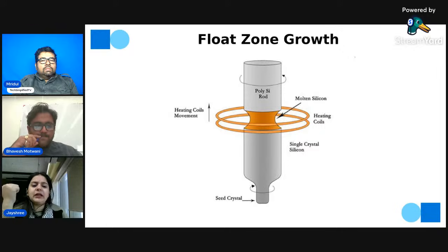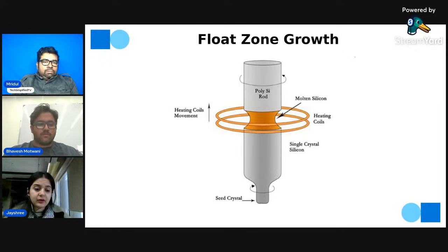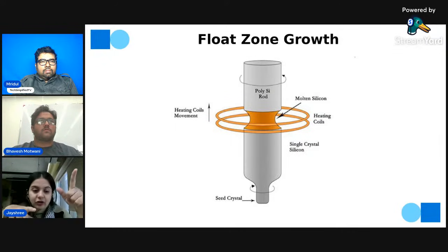Okay, then there is argon gas flow also. We should make sure that the ambient gas, which is specifically argon, is directed along the surface to cool the chamber once our process is done. And with the ambient control, the inert gases, hot graphite, and everything must be protected from oxygen, so as to prevent erosion, and it shouldn't react with the molten silicon. So that's the main step for the gas control which needs to be maintained.